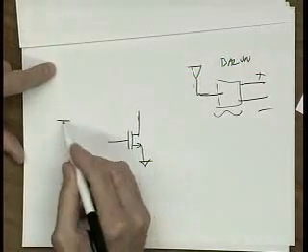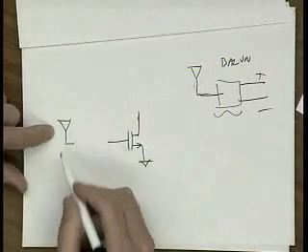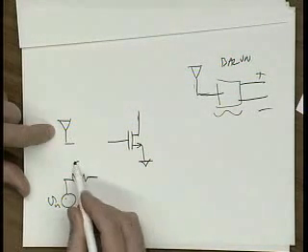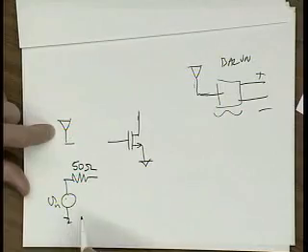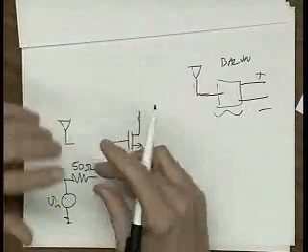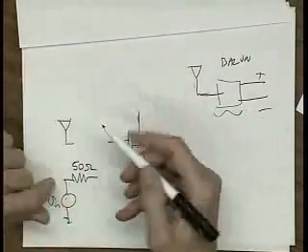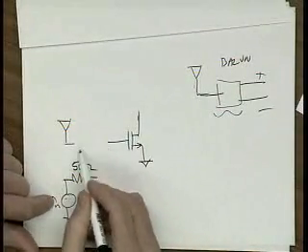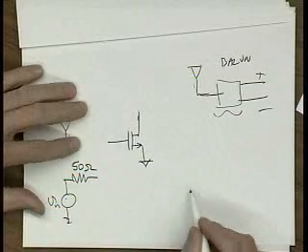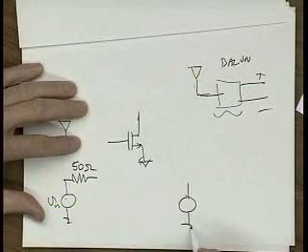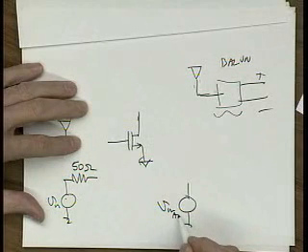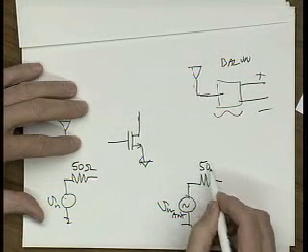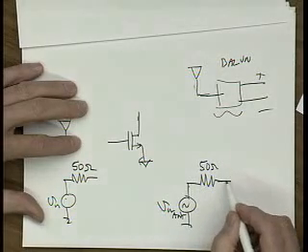And an antenna can be modeled as basically a voltage source in series with 50 ohms. We can design circuits to be different impedance levels, so let's say we could design our antenna to be 50 ohms. Basically our input looks like this. Let me just redraw this here. So here's our antenna voltage, and it goes through a 50 ohm resistor. That's modeling this antenna, and it comes into our common source.